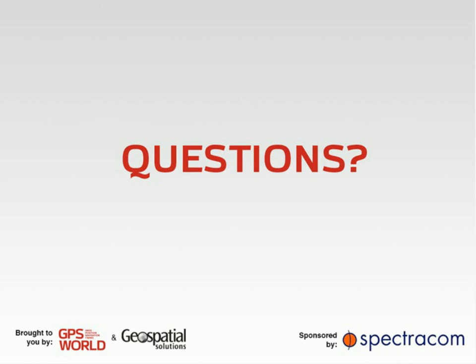Alan, this is John Fischer from Spectracom. I'll go first. In the multi-constellation, I guess it's probably more of a question for receiver designers. They're the ones that have the real challenges in designing multi-constellation receivers. But we can just share what we've observed of the challenges, which is having to test for the synchronization between the different constellations. As you may know, each one, GPS, GLONASS, Galileo, Beidou, their time references are just slightly different. They'll report on those differences. It's a very controlled situation, but there are differences, and so it's a challenge for the receiver designers to make sure that they're synchronizing that way.